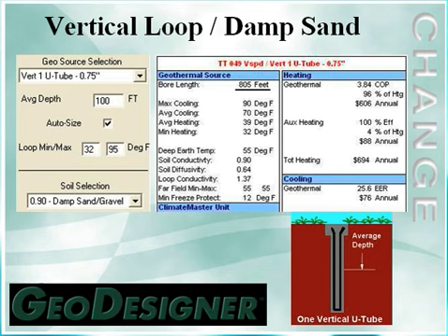So in this example today, with a 4-ton unit, I would take that total bore depth of 805 feet, divide it by 4, and I would need 4 boreholes, minimum of 10-foot spacing between boreholes, at about 200-foot depth per borehole. We'll tie that to a common header, bring our piping back into the system to our central pump.